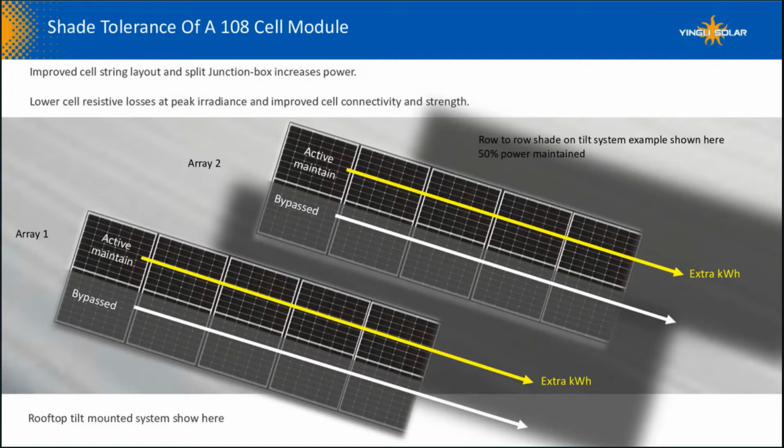We know that solar panels output, particularly current flow, is proportional to the amount of sunlight, and therefore any form of partial shade will result in less energy production. There's also other technical challenges, such as heat buildup within the cell, which may accelerate material degradation. A good solar designer and installer will therefore try and avoid positioning any solar panel in a shaded location, because even with the addition of external optimization equipment, you can't get around the fact that less sunlight means less solar power.